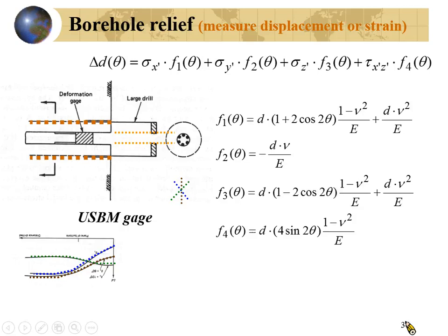When you drill the borehole, you must have some rock core. So you will have the rock here. You can do experiments to obtain the elastic constants for the rocks where you measure the in situ stress. So you use the rock core from when you drilled the borehole. Okay.